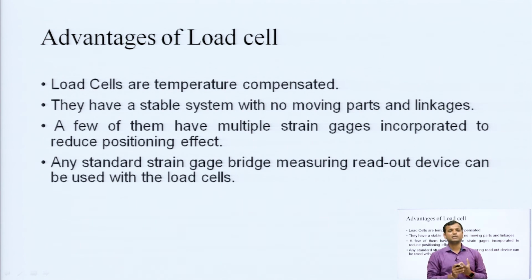So, as we have seen lastly, we have seen the displacement measurement. In that we have used mechanical devices to measure the displacement. So, when we use a mechanical arrangement to measure the displacement, we have some type of friction losses because of the moving parts we are using. But in case of load cell, when we are measuring the force with the help of load cell, we do not have any type of moving part. So, that is one advantage of load cell.